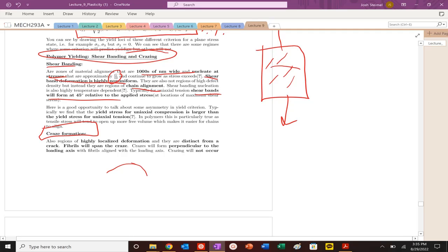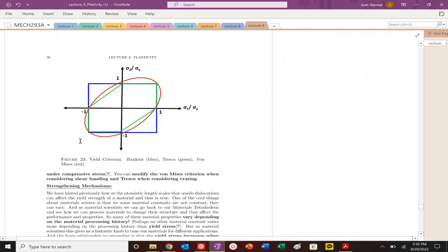So what you'll find is when there is a micro crack or a micro void appearing, crazes or fibrils will form that connect essentially the cracked faces. And it's this cool combination or competition between stretching and surface area creation.